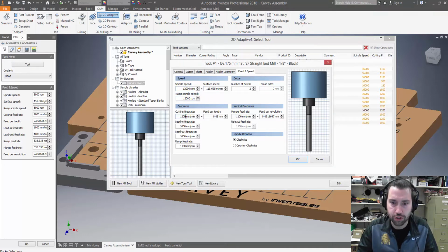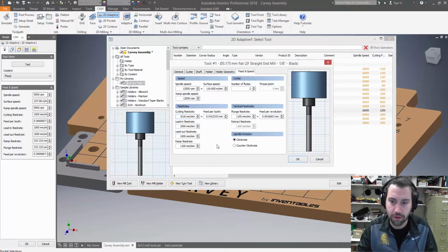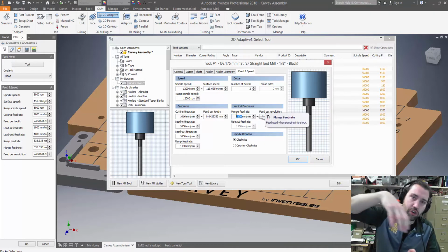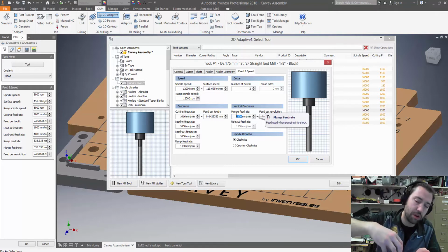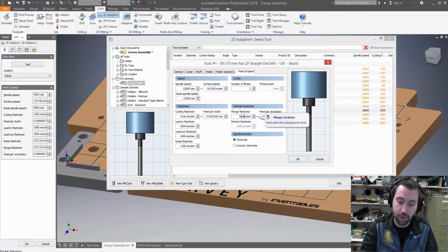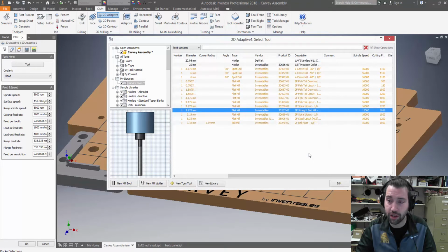Our feed rate should be 1016, and our plunge rate, this one's actually drastically different. The Xcarve can be much more aggressive in basically how much material it takes at one time. So this would be like on a new layer of carving, how far do we go down? And we want to have a much slower rate than that. We want to use 304 as a feed rate. So if we make those 3 changes and hit OK, we'll have an updated one.